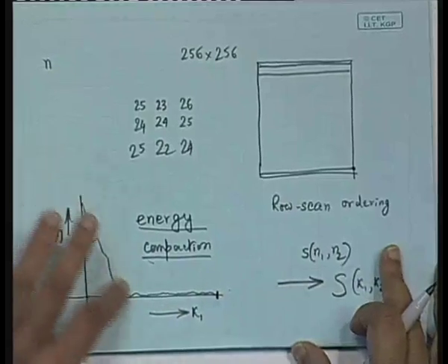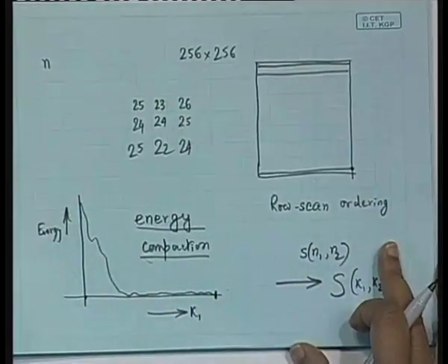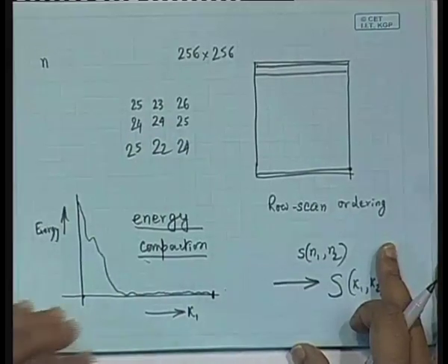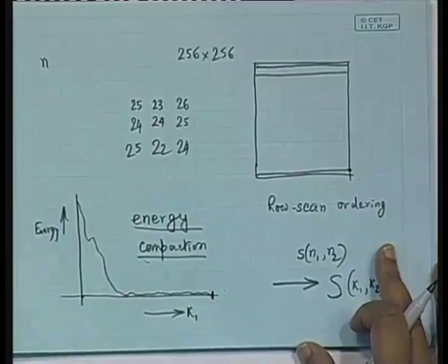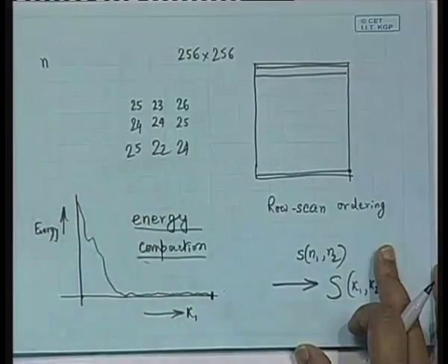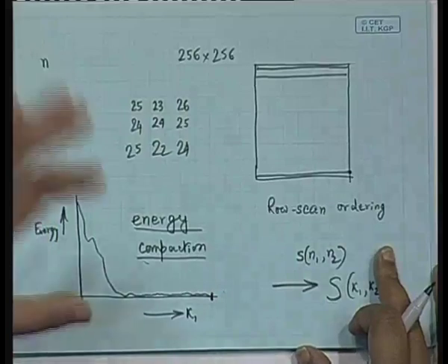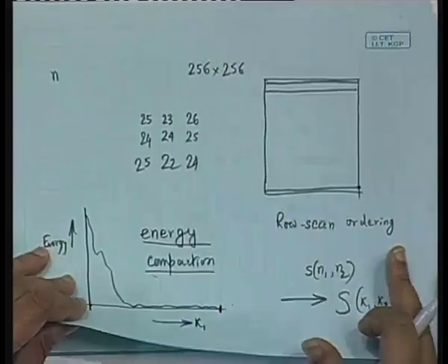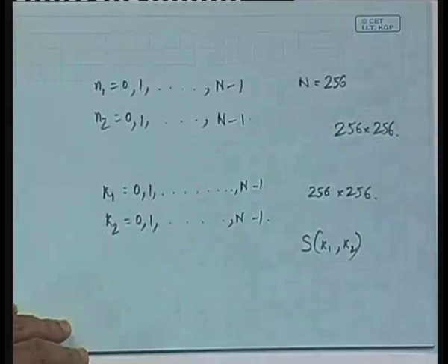We could not get this picture in the original spatial domain, but we can get it after studying the redundancy that is present in the original picture domain, and the redundancy is best depicted in the transformed space. While carrying out the transformed space analysis, we will find that there is energy compaction, and that energy compaction essentially leads to the fact that we can achieve a good amount of compression, if we first use the transformation followed by a quantization.